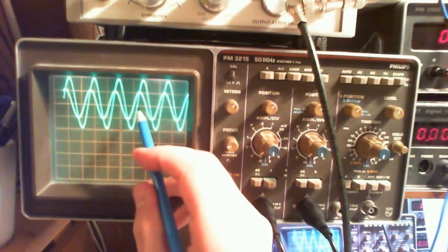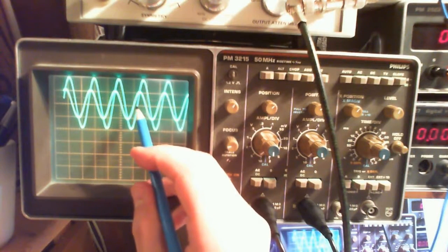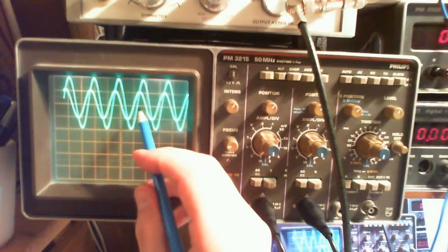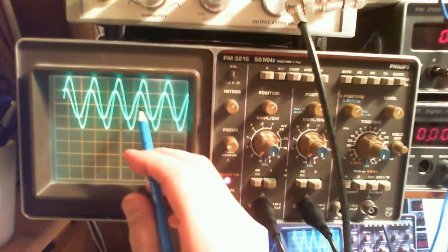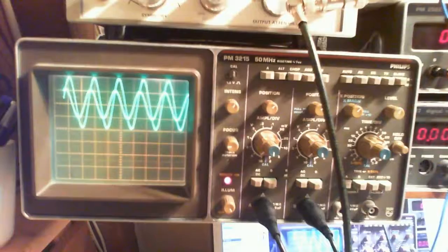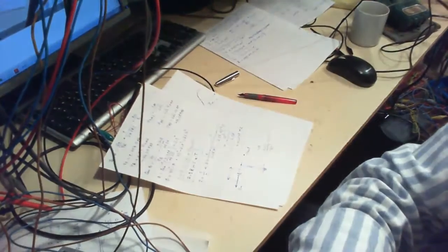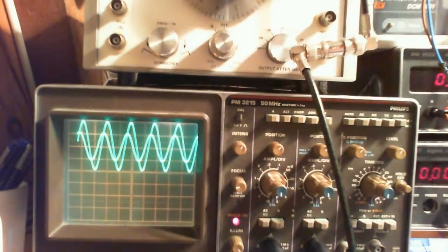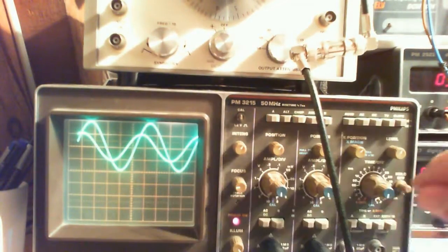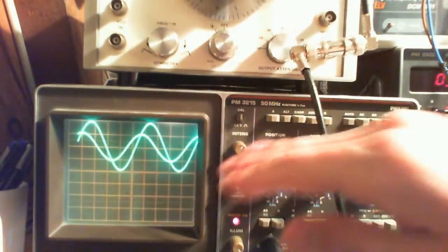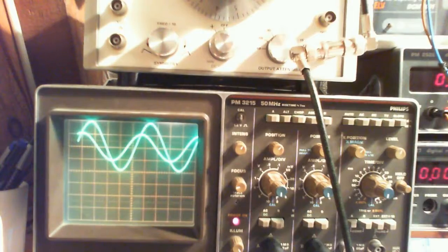So if you compare these 2 points, each graduation is 0.2, and let's say this is 1/2 of 0.2, so 0.1, so the difference is 0.3 horizontal units. Okay, not very good. What I should have done is zoomed in horizontally more on my signal so that I could read my signals better.